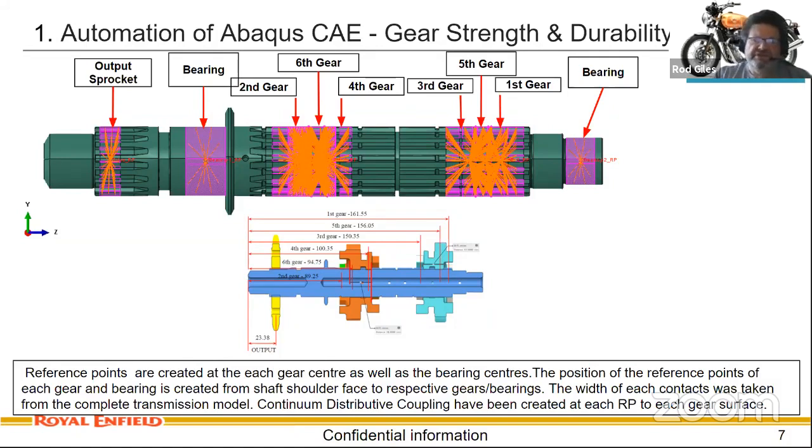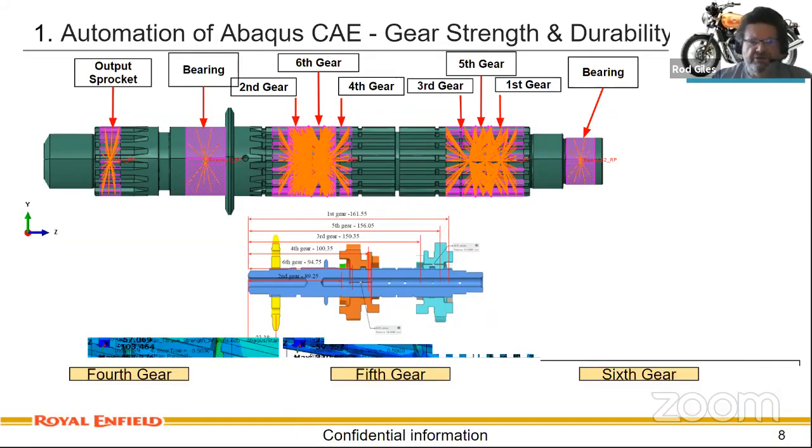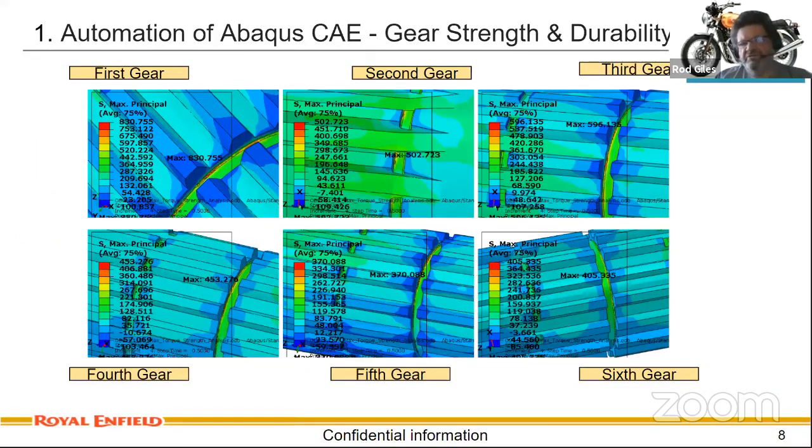And this is now completely automated, so we just need to bring the shaft in, fill in the dialog box, and the output is the ODB. And then we also have another application that reads an ODB and creates a report file. And so this is just a single slide from that report.